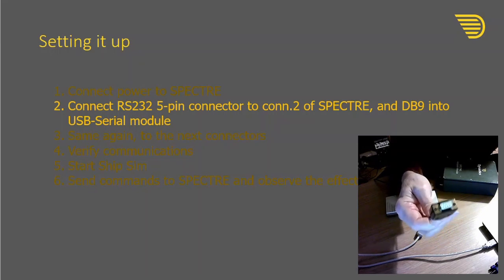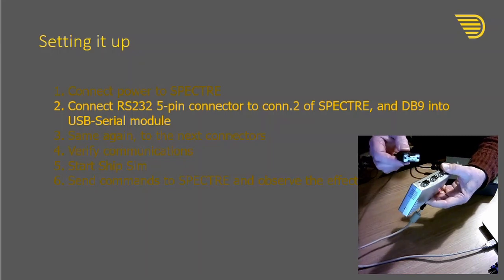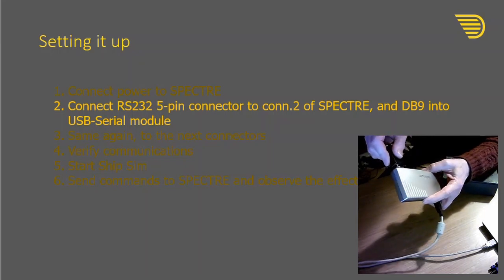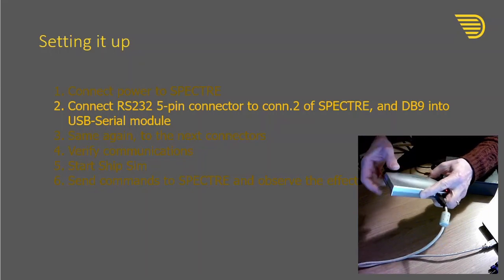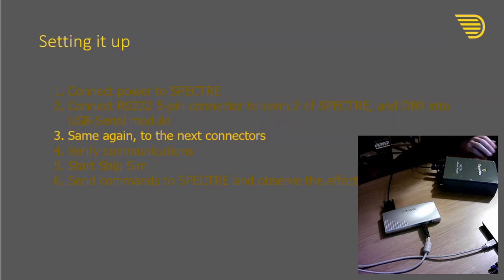So that DB9 is serial communications, is absolutely standard pinout, and that goes into number 1 here of the USB serial module. That's good. We're doing well.